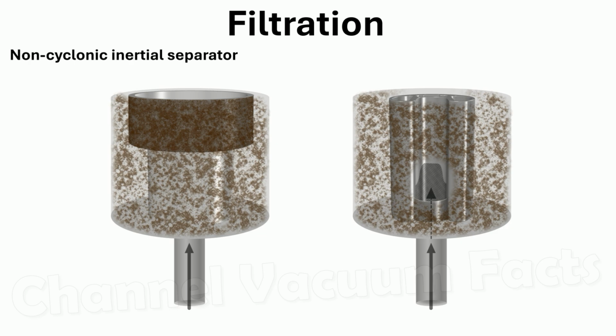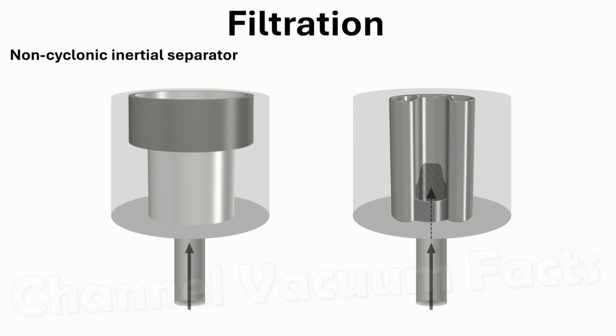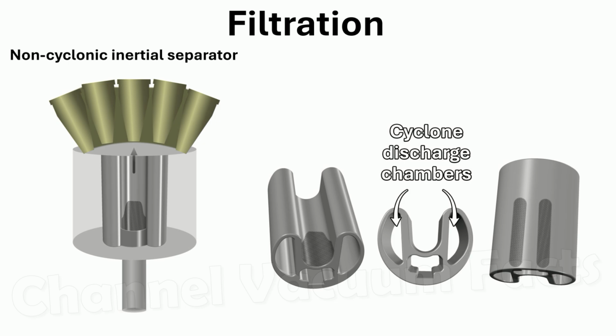The shroud shouldn't now block up before the bin is full, even when upside down, because the main flow into the machine and through the primary mesh is isolated from the accumulated dust in the main bin. It also gives more bin space to hold more dirt. The air from this system then heads on to a traditional cyclone pack for removal of much finer dirt before heading to the filters.